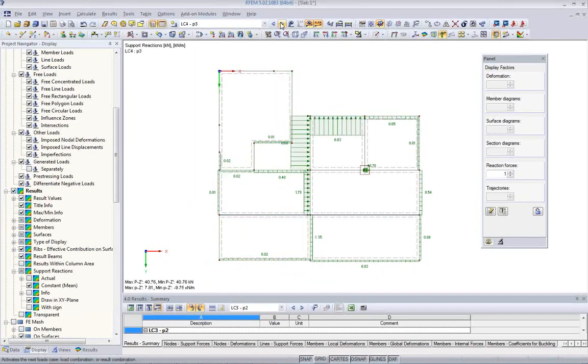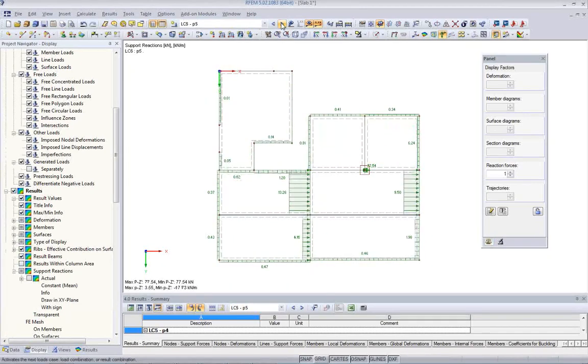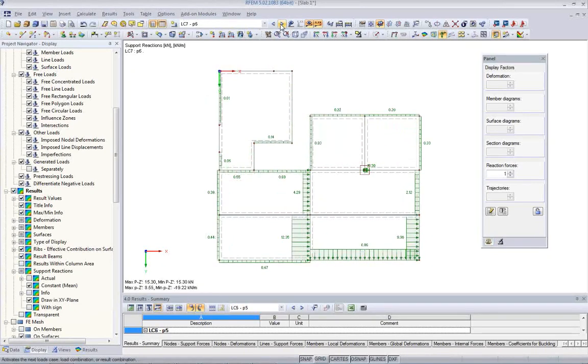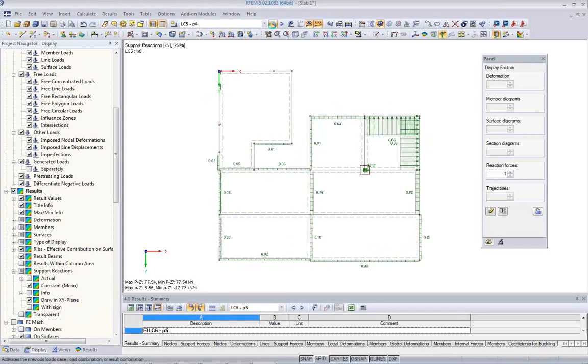What we do is integrate all the support forces along the line and average them to a mean value. This is a good way you can maybe use this information also for a load on the next story that you have maybe below.